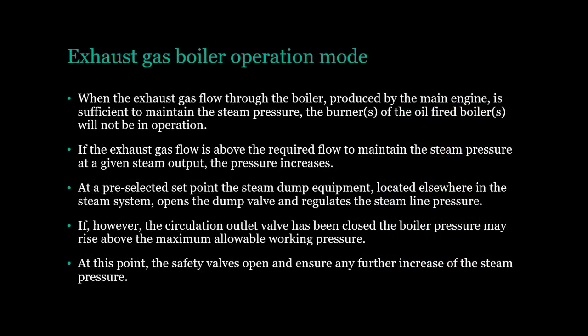Exhaust gas boiler operation mode. When the exhaust gas flow through the boiler, produced by the main engine, is sufficient to maintain the steam pressure, the burners of the oil-fired boilers will not be in operation. If the exhaust gas flow is above the required flow to maintain the steam pressure at a given steam output, the pressure increases.